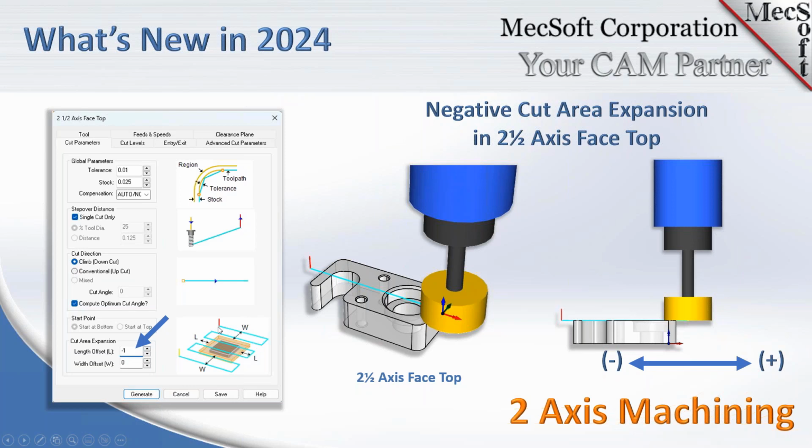If you look at the icon in the dialog, what this operation does is it adds distances to the maximum size of the part in the stock. Previously you could only add distance to the tool path, move it out, but you could never move it in. Now you can enter a negative value here, and that'll tighten up your tool paths and save you a little bit of time.